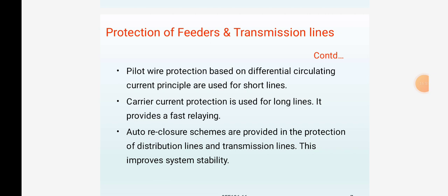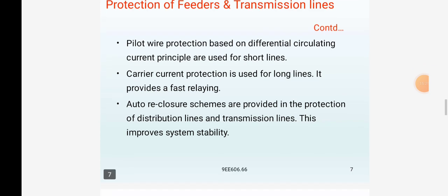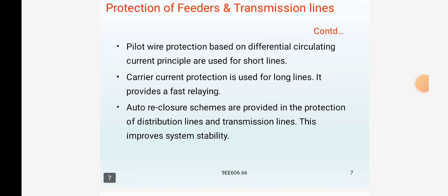In the figure, this type of layout is shown in the case of a large generating station having two generators and two outgoing lines connected through step-up transformers. The use of a bus bar coupler BC converts the duplicate bus bars into a ring system, which has greater flexibility. So, this is the basic concept about protection of bus bars.